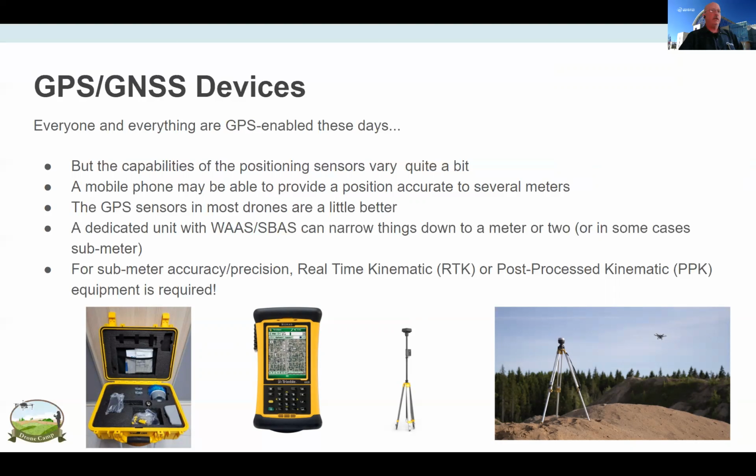But if we want to really nail things down, we want sub-meter precision. And in order to accomplish that, generally, either real-time kinematic or post-process kinematic, these are both kinds of differential GPS. Those kinds of techniques are really what's needed.